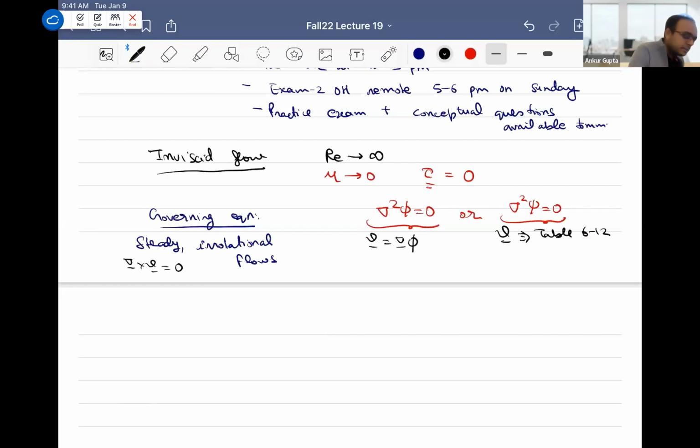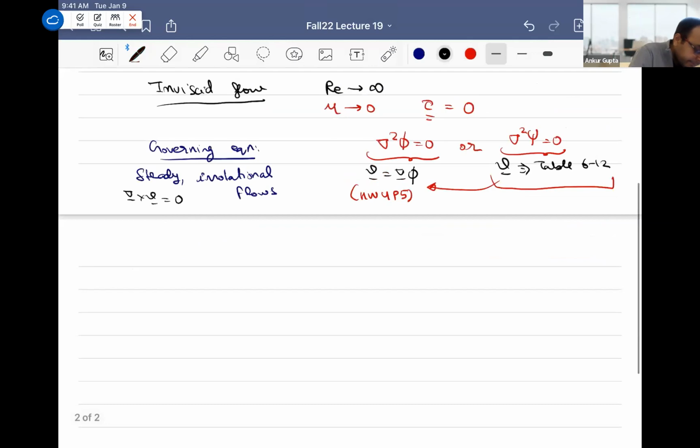So in the class, what I will do is I'll do a problem with this approach. In your homework, you use the grad phi approach. So you can see both approaches. Any questions? Sorry, maybe I was not very good with writing. This is psi actually, and this one is phi, the first one. So phi and psi. We can have the potential in case we have the velocity. Homework 4 problem 5 shows you this approach, and in the class we will do the psi approach. Once you do this, find velocity, and then use Bernoulli's to find pressure.